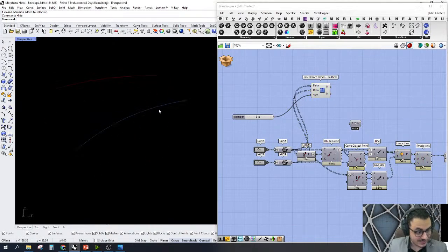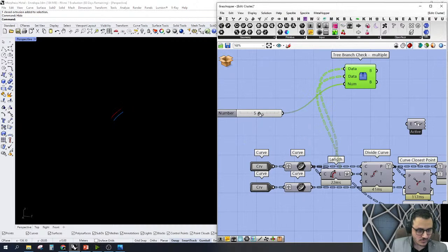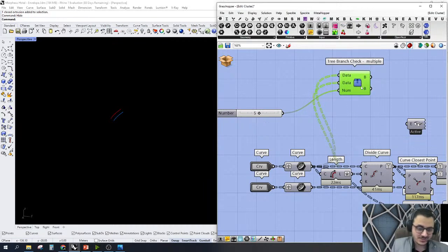You can see that this is the glazing layer that I want the structure to respect, and this is the structure. This is the curve for the structure, and wherever I go, of course, I want the curves to be oriented to the structure, to the topology of the building, and that's why I had to make sure that the item indices are the controller of the data tree. That's exactly why I did it.